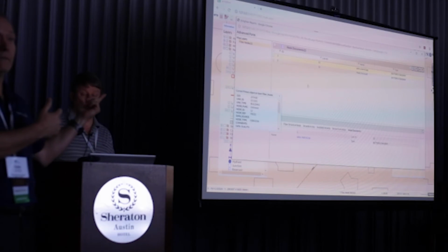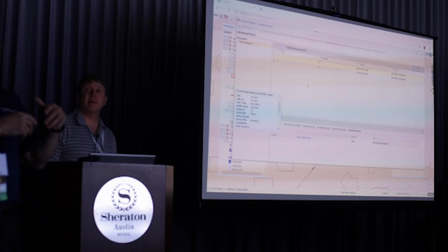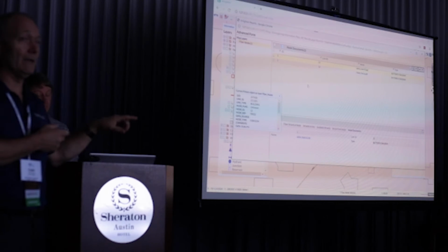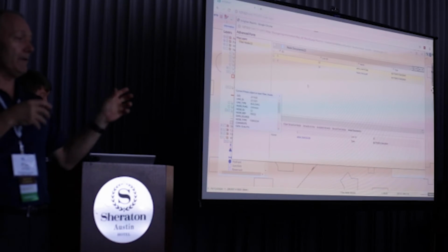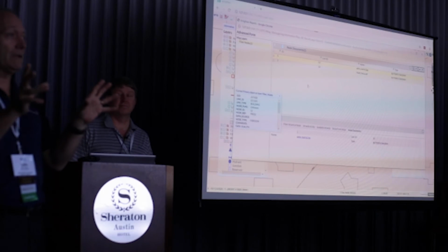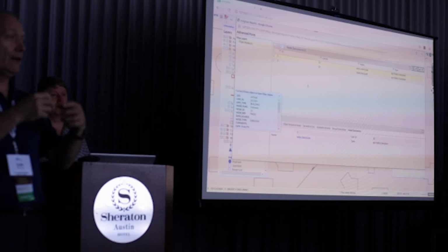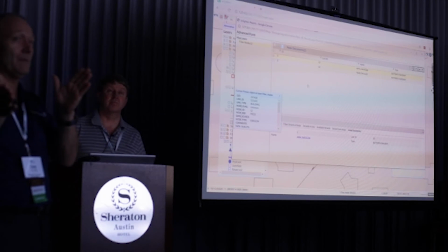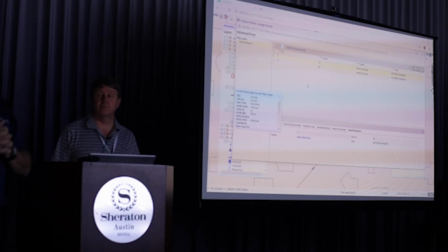So I think that PDF was just mapped to a physical location somewhere on the network. But that could also be a URL document. So if it's in Meridian, for example, you can have a URL that will build that. In the product here, we allow you to put in a prefix and a suffix. The prefix would be the name of your server and everything else, and the suffix could be anything. But the actual value, the unique ID of that particular node or cable segment, would need to correspond to somewhere in your document management system, or one of the fields that you may have within it. So that's how you'll link.